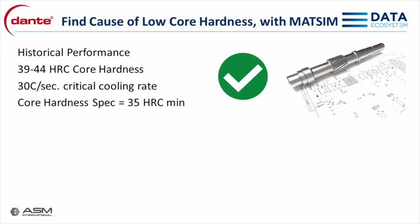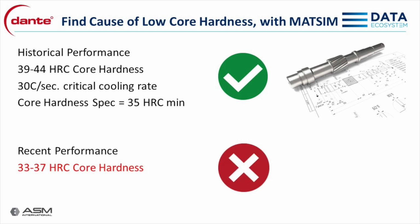You've been successfully making a part out of AISI 8620 for a long time. You know your steel distributor uses a number of different mills, but your part has been supplied by only one of those mills. Hitting the minimum core hardness spec of 35 Rockwell C has been a snap. You're usually over 40. The bad news is lately you've been struggling to hit the minimum core hardness and you don't know why.